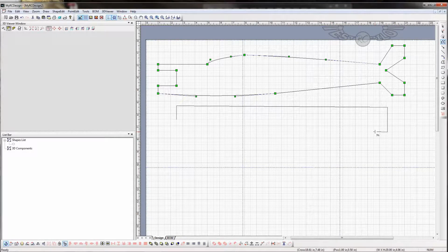We'll do that and that. And come up to where the wing is going to be, and you don't want your aileron to be right up against your plane because you want some of the wind to be able to move past the wing and hit the elevator when you're flying in 3D. So we're going to give it about an inch of space here, and then a cutout for the elevator, or I mean the aileron. And then come on up here for the end of the wing.